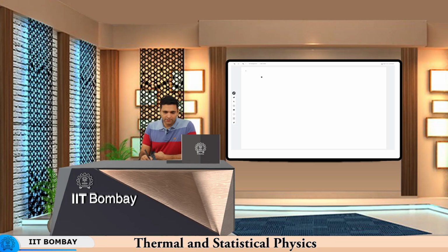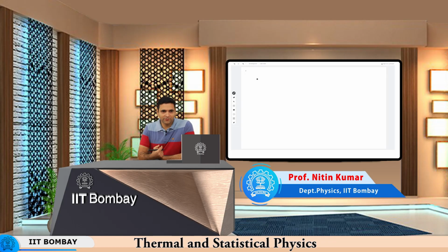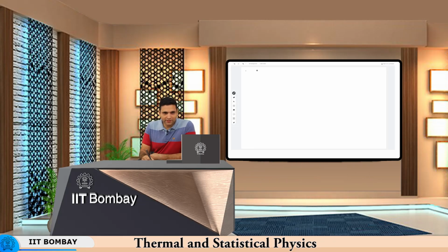Alright, so welcome back. In the last class we looked at the thermodynamics of phase transitions, and a very important equation that we wrote was known as the Clausius-Clapeyron equation, which is del P by del T at constant V equals latent heat divided by temperature times (vf minus vi), where small vf is the specific volume of the final phase and small vi stands for the specific volume of the initial phase, during the phase transition.